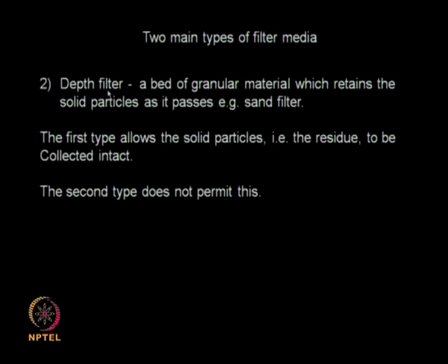The other approach is the depth filter. So you have a bed, a granular material bed of varying particle sizes, granules, pebbles, sands, which try to capture the solids present in a fluid. Especially this type of depth filter is used in water treatment facilities. They are also called sand filters.